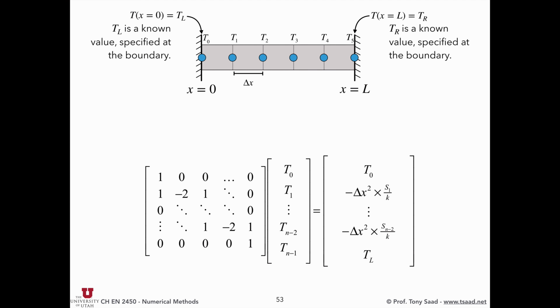So we're going to program this system of equations in Python and then define a source term. We'll pick an arbitrary source term, maybe a Gaussian distribution where it's zero everywhere along the rod, and at the center the volumetric heat transfer peaks and then goes down to zero, so there's some heating in the middle of the rod. Then we'll solve it with the built-in routines in Python, direct solve or A inverse, and then we'll call the Thomas algorithm just to show you how this works.